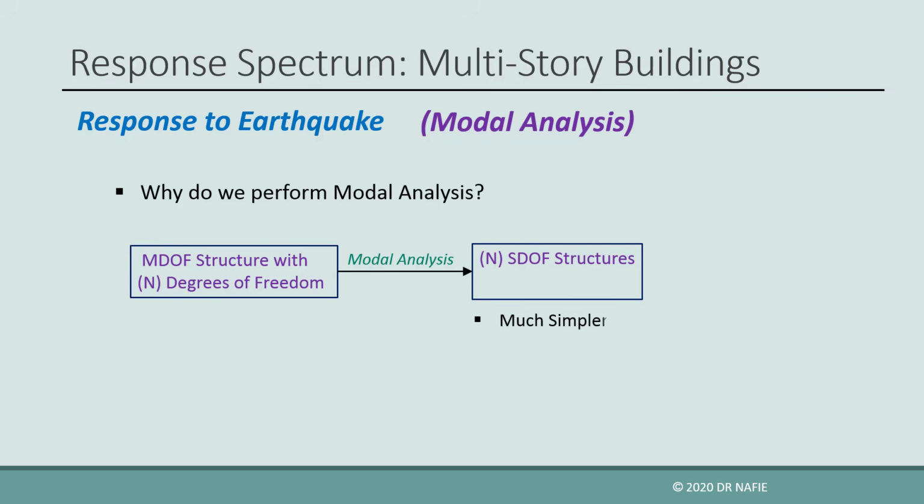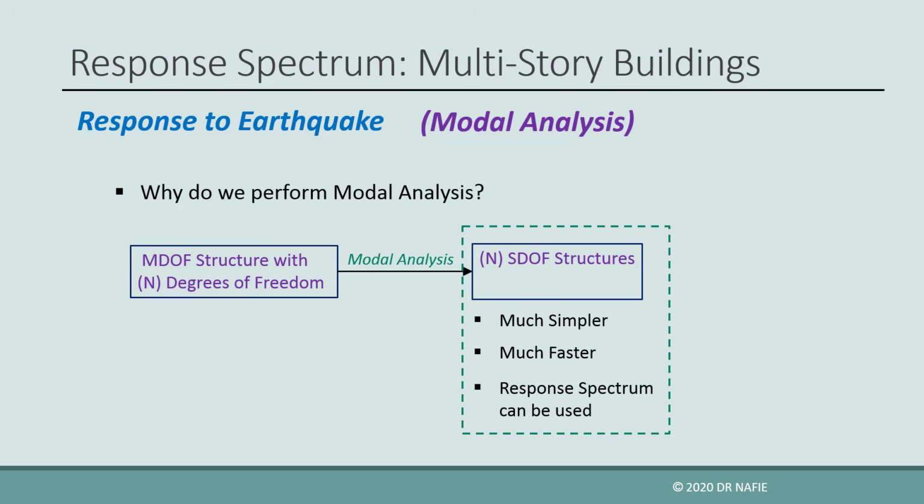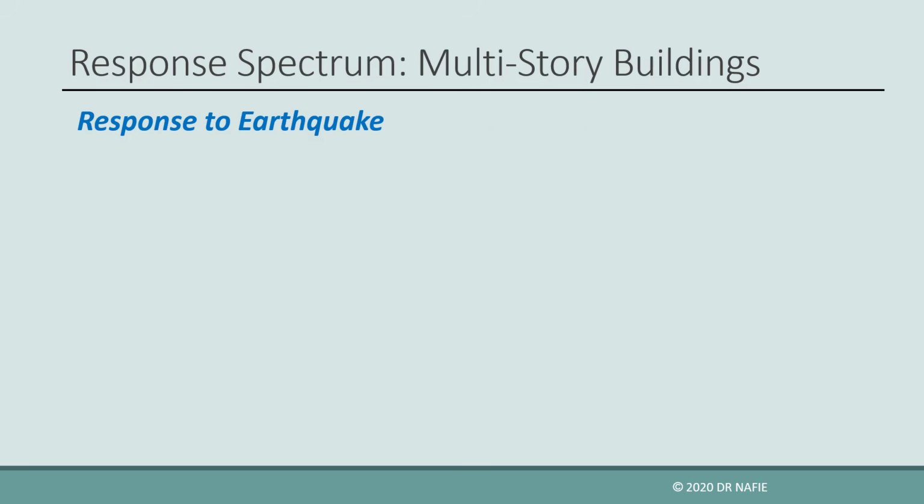The analysis becomes simpler and faster. More importantly, we can apply the methods of the analysis developed for the single degree of freedom structures to multi-degree of freedom buildings. Therefore, we can apply the response spectrum analysis to multi-degree of freedom buildings using modal analysis. One major problem of the modal analysis, however, is that it is based on superposition and therefore it is not suitable for nonlinear analysis. Now, let us explore how to use response spectrum curve with modal analysis.